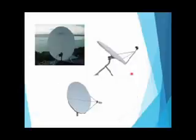The new DBS system uses compressed digital video to lower the data rate and improve reliability of transmission. Once the video signals have been put into digital form, they are processed by DSP circuits. The DBS satellites use the Ku band, with a frequency range of 11 to 14 GHz. So this is a sample of the Ku band.